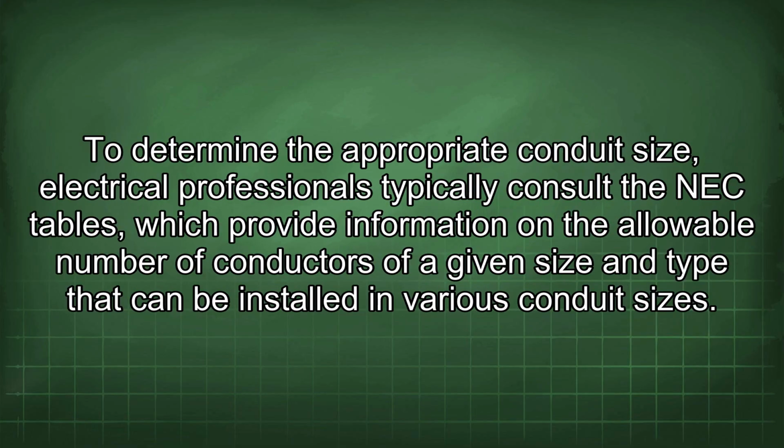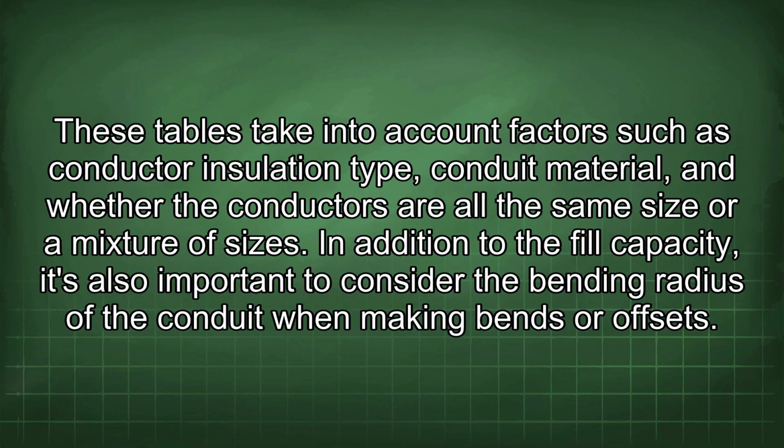To determine the appropriate conduit size, electrical professionals typically consult the NEC tables, which provide information on the allowable number of conductors of a given size and type that can be installed in various conduit sizes. These tables take into account factors such as conductor insulation type, conduit material, and whether the conductors are all the same size or a mixture of sizes.